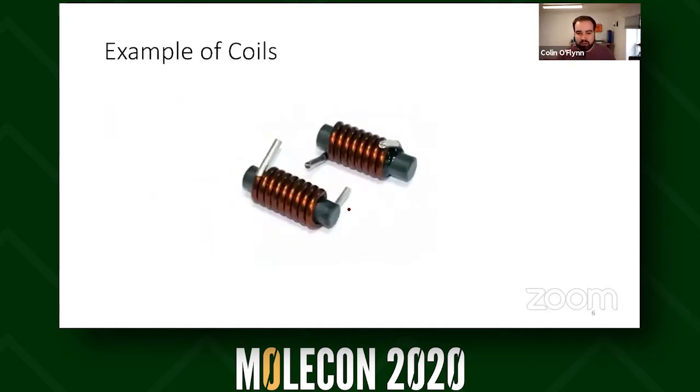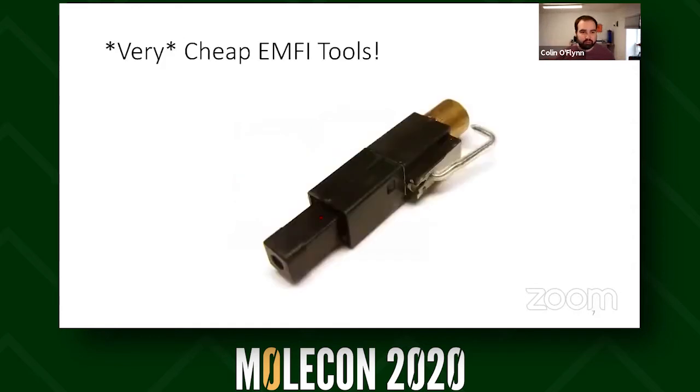And when I say a coil, it's something like this. So these ferrites, you can get, and then you can just wrap a few turns of coil around it. These are even off the shelf inductors designed for use in electronics projects, but something like that actually works pretty well as an example coil. There's quite a few examples out there. The end goal is you want to drive a bunch of current through this coil to generate a strong pulse. You can do pretty similar things with a piezo lighter.